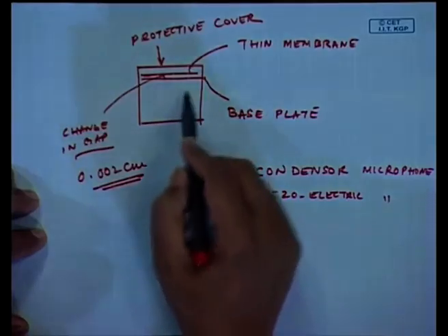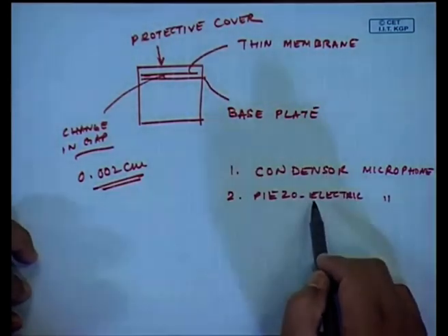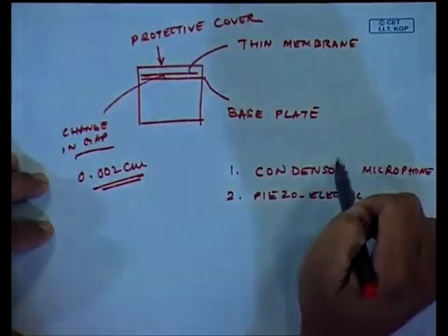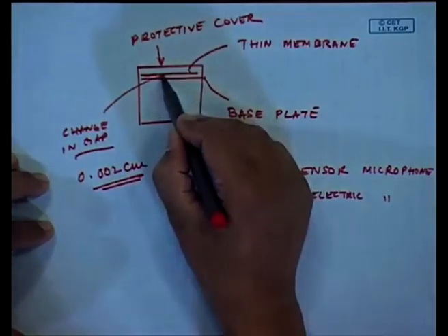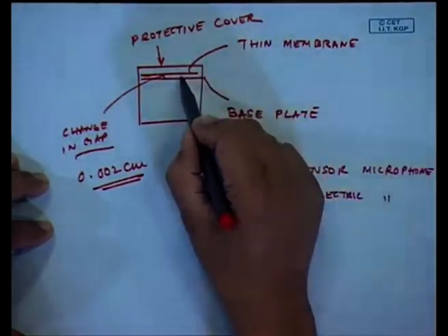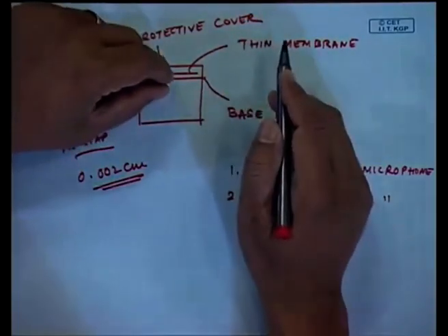open. So, what happens, either be it condenser microphone or piezoelectric microphone, the only difference is that in the case of a condenser microphone, because of the deflection of the membrane here, this gap is going to change. So, the capacitance between these two plates is going to change.